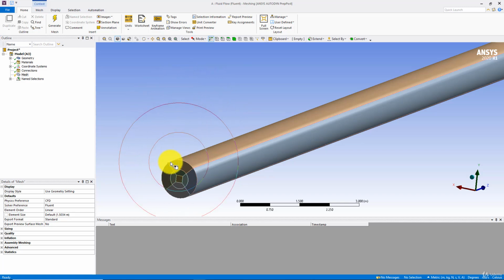And resolution is in your control. You can precisely control where you want to have the refined mesh. The downside is that we need various operations to decompose the geometry, which may be difficult or cumbersome, especially in Ansys meshing where we need to divide the geometry into multiple parts. While in ICEM CFD, we divide the blocking, not the geometry, but on the blocking side. So it may be much easier. But anyhow, hexa meshing in any software requires a lot of work. So this is the downside.